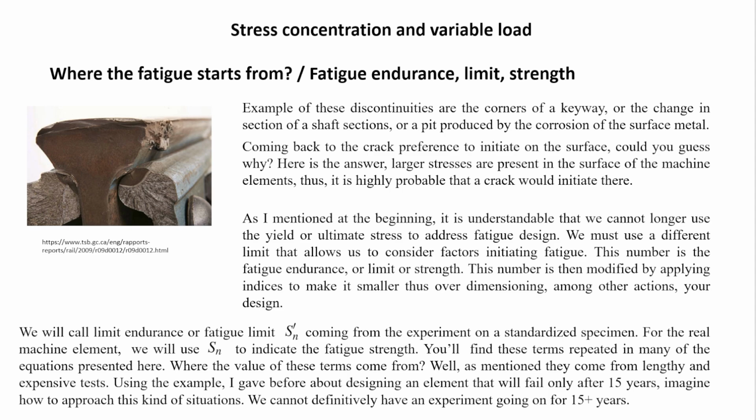The number we need to take care not to exceed, because if not we're going to be prone to a fatigue failure in our design, is represented in several ways, like Sn or S prime n, and is called the fatigue endurance, endurance limit, or fatigue limit.